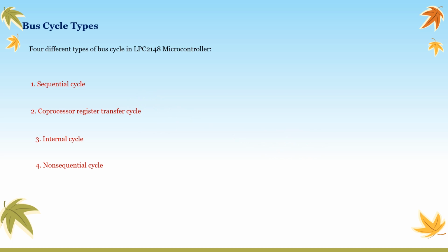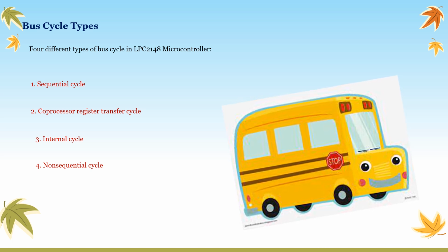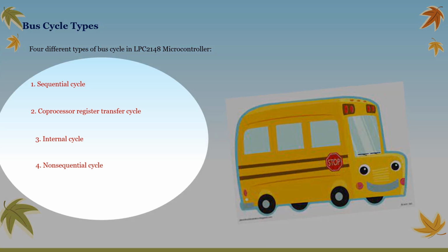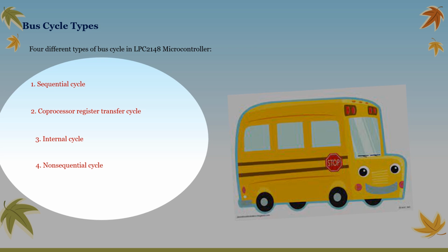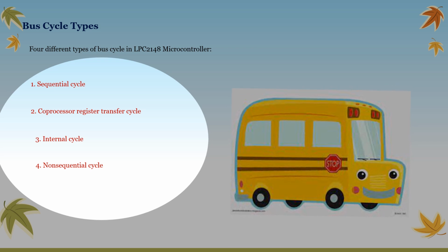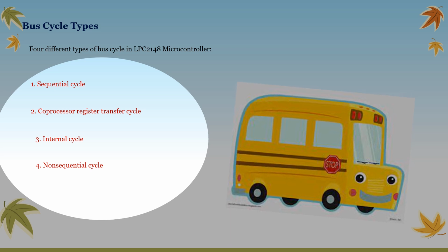Let's see what memory is in a microcontroller and its working in ARM microcontroller. The bus cycle is the cycle, or time required, to make a single read or write transaction between the CPU and an external device such as external memory. The ARM7TDMI processor bus interface is pipelined. This gives the maximum time for a memory cycle to decode the address and respond to the access request.